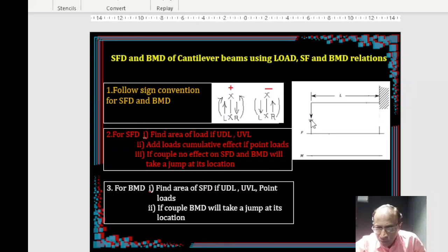So whatever are the loads, keep adding the loads. That's what you have to do. You don't have to multiply the loads with the distances also. It is not a UDL, right? So you can simply keep adding the loads. There is only one load, right? So that load, according to the sign convention, when you are on the left of the section, downward forces are negative.